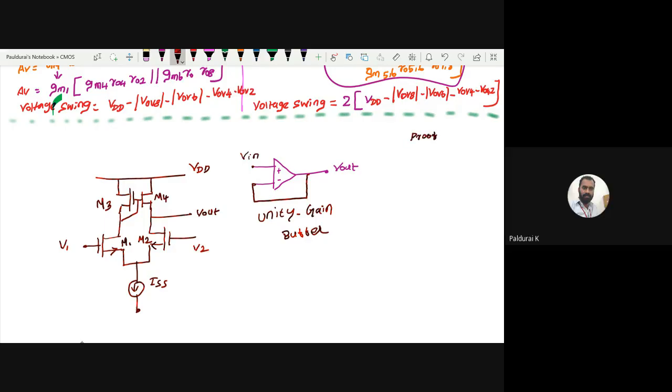This is what I had asked, find the loop gain, right? 2 mark question. Nobody did it correctly. I asked for the loop gain. Unity gain is nothing but my feedback, right? Yeah, feedback factor beta equal to 1. But here there is some gain A. I am asking A beta. So where beta equals 1, so it is the loop gain. That is what Naveen is saying, loop gain is A.